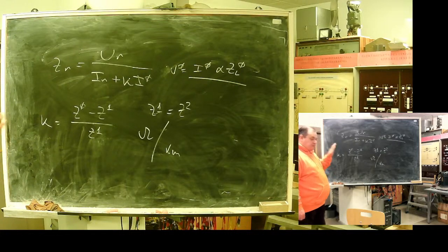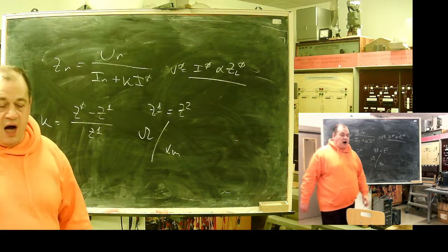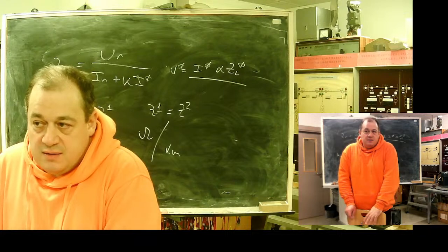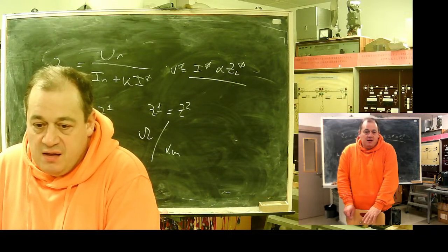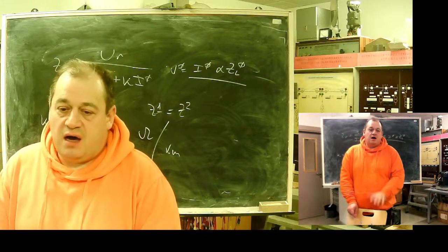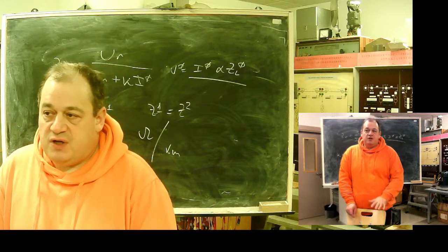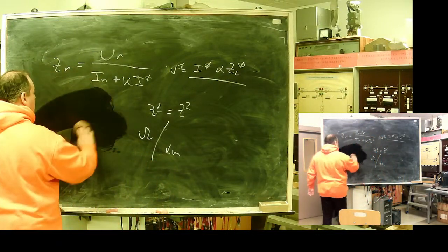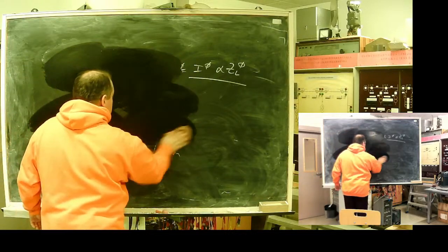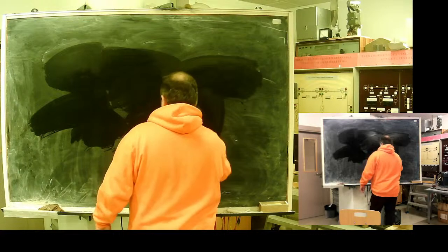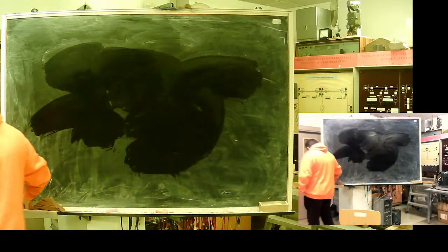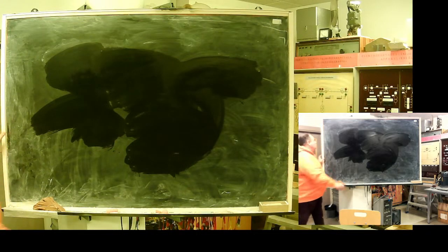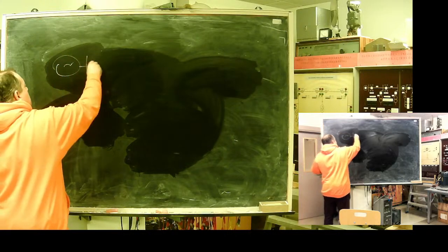Now we know the new values. I can start considering the influence of transient resistance in more detail. When we know how distance relays are calculating fault resistance, let's come closer to reality.